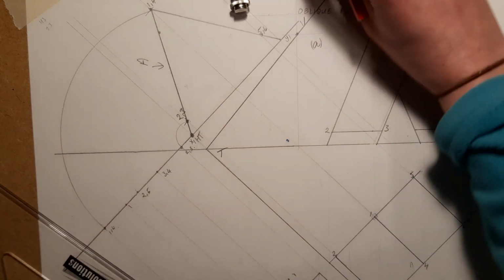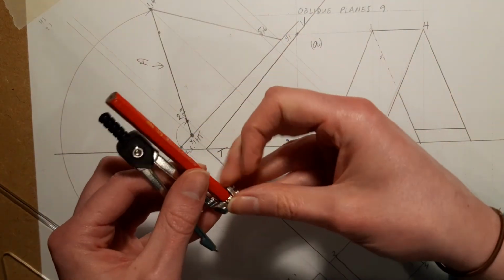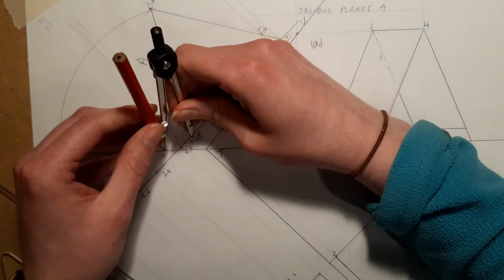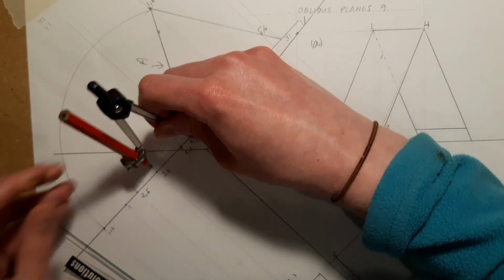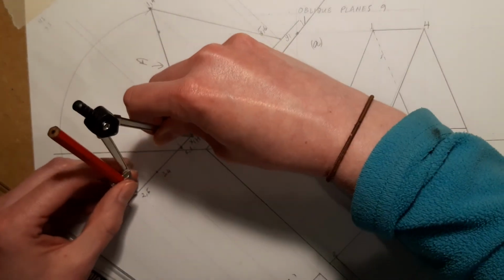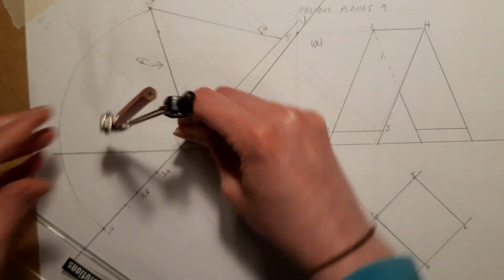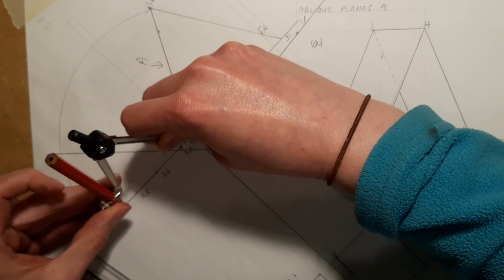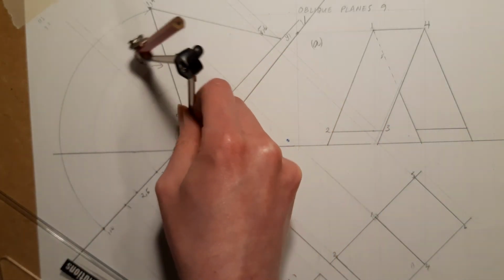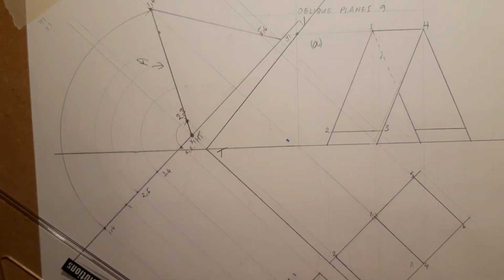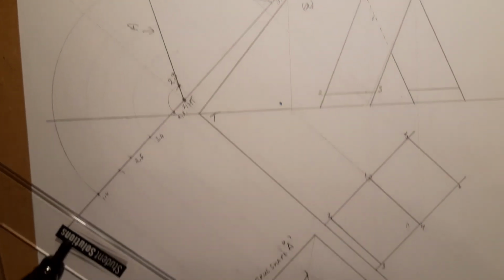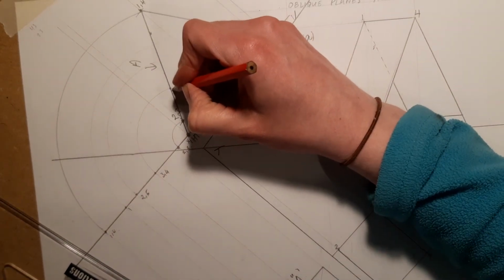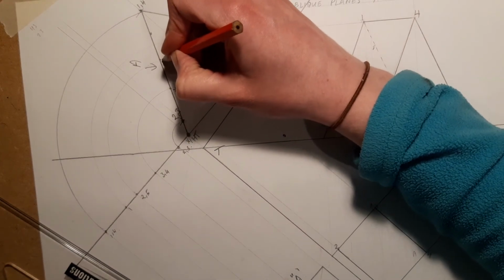Okay. So compass. Compass goes on the HT or XY line, whatever you want to call it. Rotate 3 and 4, rotate 2 and 5, and rotate 1. Okay, so it's actually testing a good bit of stuff, this question. It's going back over everything you've kind of learned about symmetry and that from first, second and third year. How to get the centre of a shape, how to draw a pentagon inside in a circle, and then how to transfer points. So we have 3 and 4, we have 2 and 5.